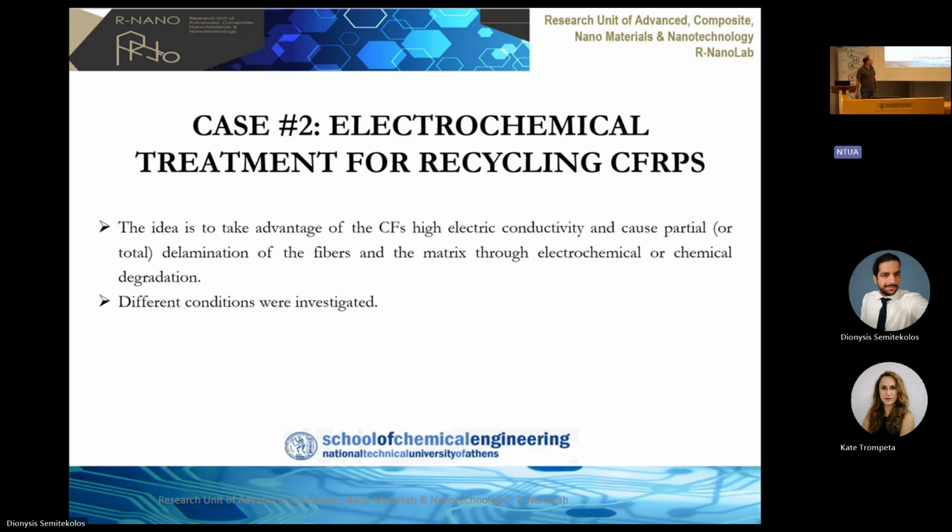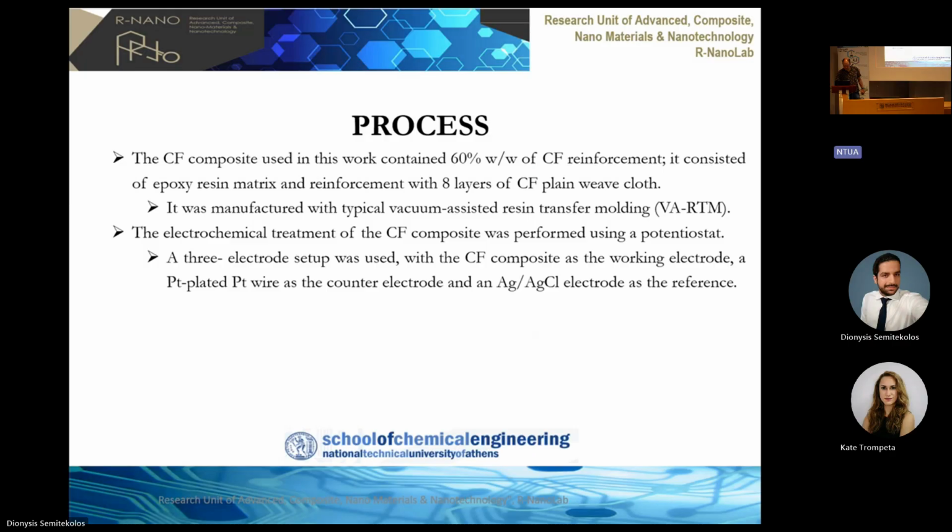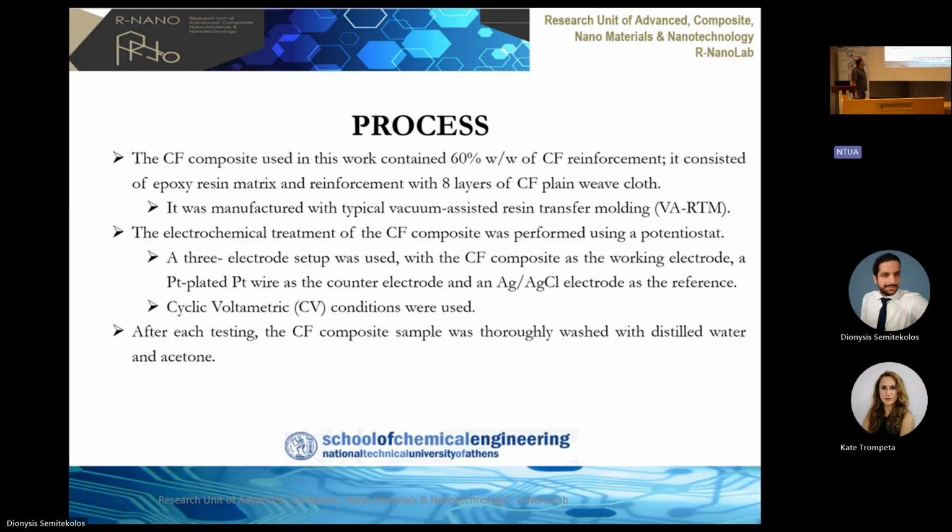We investigated different conditions. We used a carbon fiber composite that contained 60% reinforcement in the form of a plain weave cloth. It was manufactured with the typical vacuum-assisted transfer molding we use in the laboratory.